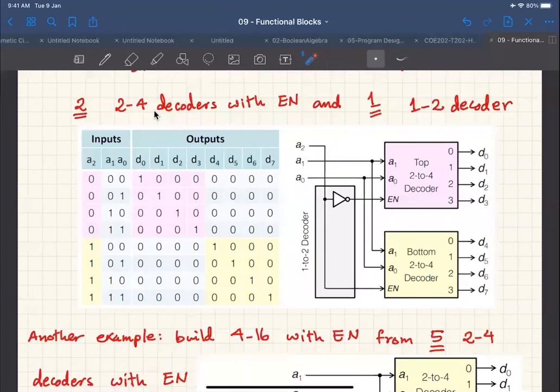So look at this table. What does it show you? As a whole, do not disregard the circuit on the right. What does it implement to you? These are the inputs and these are the outputs. 8-bit decoders? No, it's not called 8-bit. It's a 3 to 8 decoder.